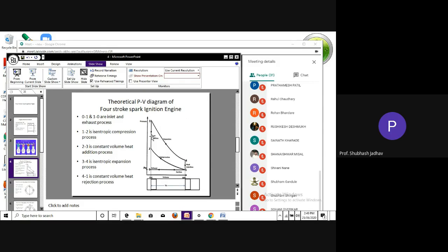So what is combustion? Burning of the fuel in the mixture, and the vapor getting converted into different burnt gases. That chemical reaction was happening over here in actual, but we assume that it is instantaneous, and therefore we call it constant volume. Here also we have assumed this is happening at constant volume, even though nothing has happened, we have assumed that it is a constant volume process, the heat rejection process.